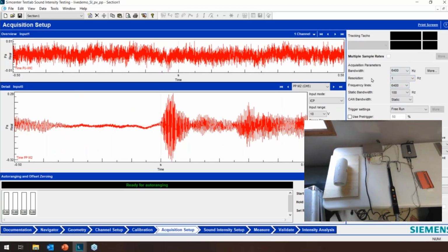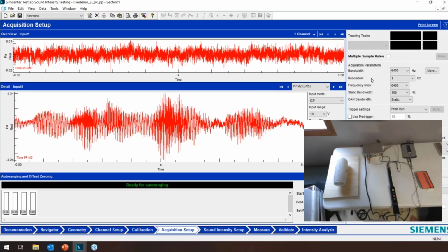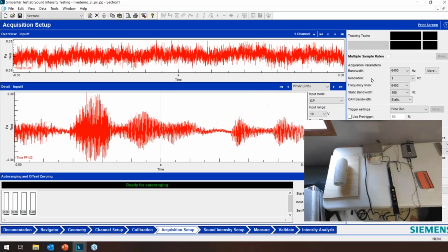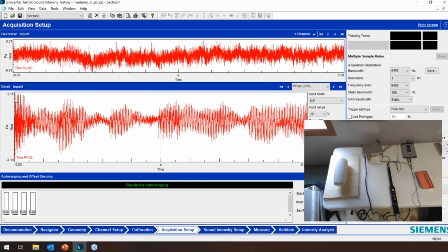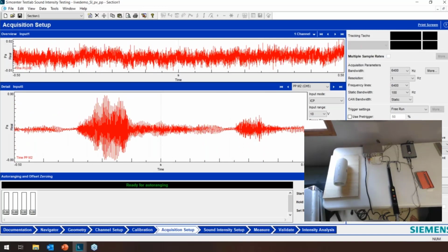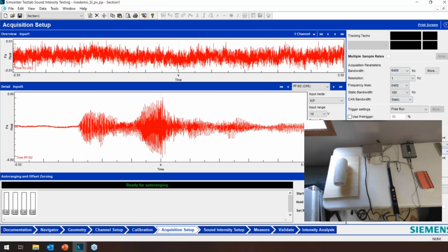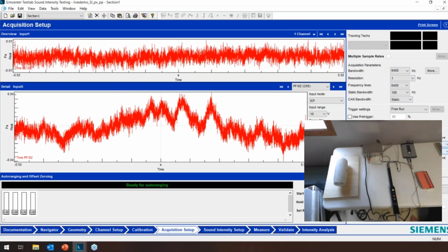This is going to make sure that we can see everything on a 1 hertz per basis. Every frequency that we get out of our measurement system will be on a 1 hertz axis. So it'll be 1000, 1001, 1002. So we have a lot more resolution with that. Windowing looks good. All this stuff looks good to me.